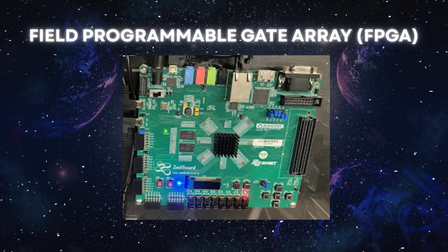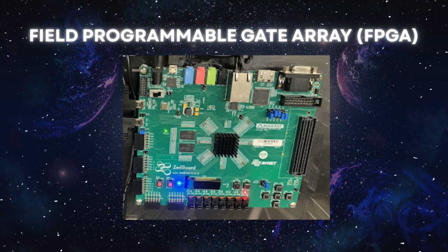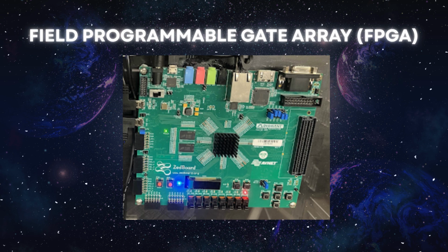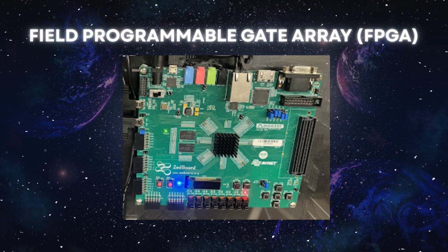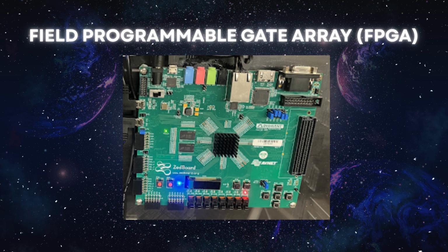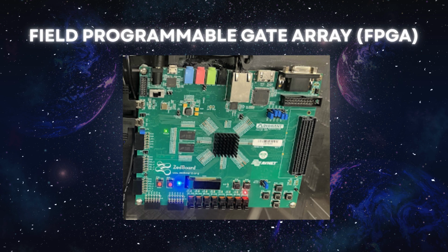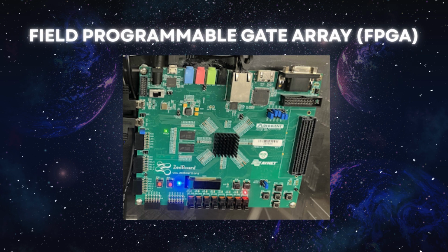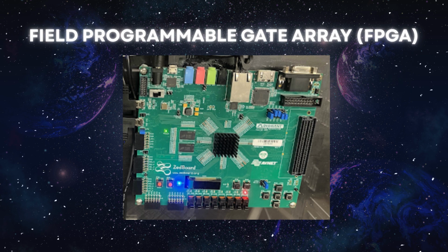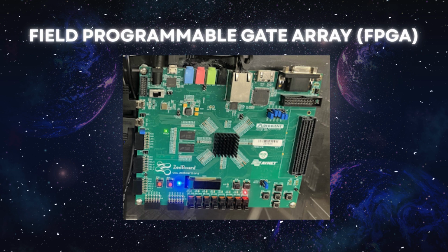Our design process begins right after the data reaches the FPGA. We start by simulating a frequency plane to extract specific tones and determine the necessary resolution and channel spacing for the MKID readout. We then develop a fixed point model of the Polyphase Filter Bank in MATLAB and in Xilinx to simulate and verify the design's performance.